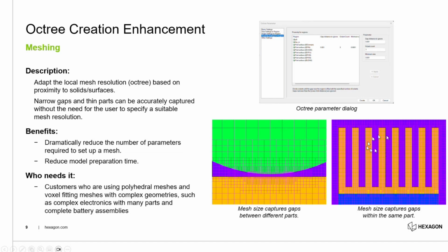Now, previously, I could have done something similar by saying for the outer surface of this fin, refine it to that level. But if I kept it at that, it would have immediately transitioned to larger elements and then the smaller elements again. So the next level would be to say, use more than one layer for that fine mesh. But the problem now is it's going to grow in this direction and in that direction. And if this is part of a larger part where there are regions where we do not want those smaller faces, it's going to be an issue.